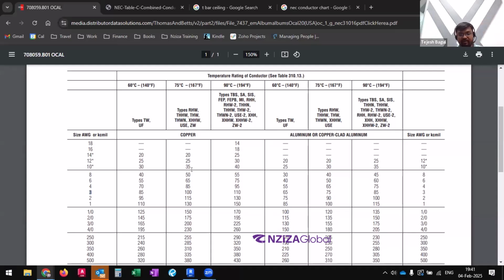All right. So when you have an underground wire system going on, you need to make sure that you give proper protection to that conductor. Basically, the conduit should be rated for that kind of use, versus what you might have in your room. In your room, you don't necessarily need the same rating for your conduit as for the underground conduit.